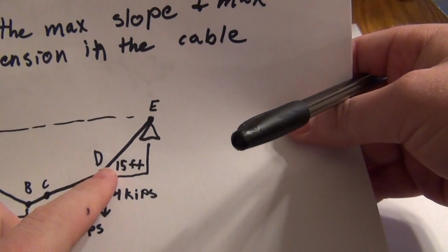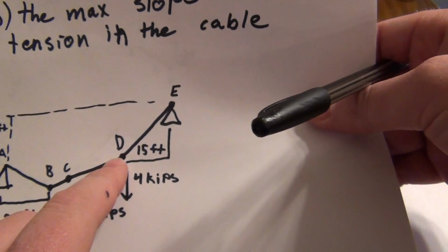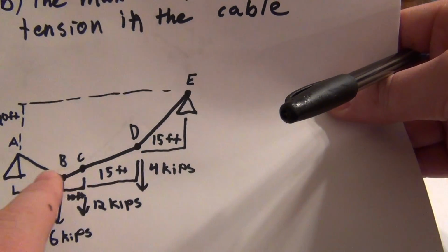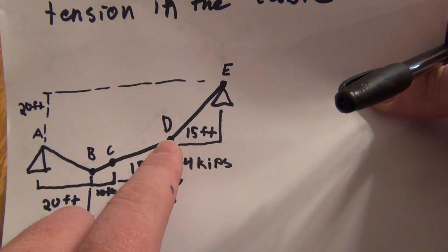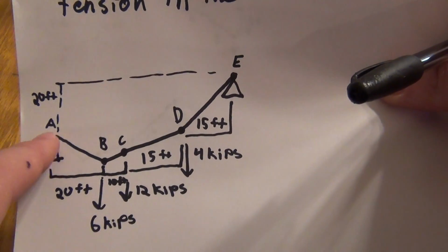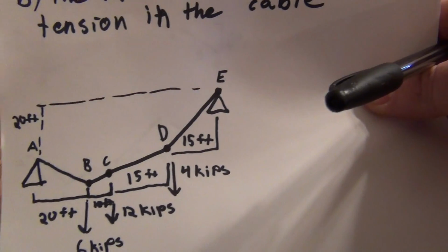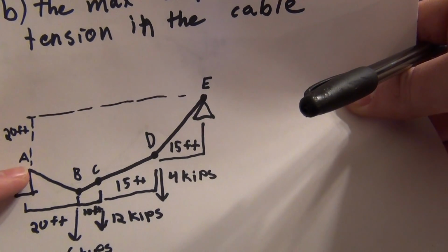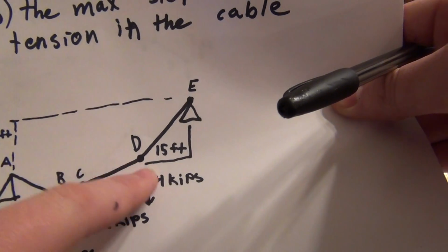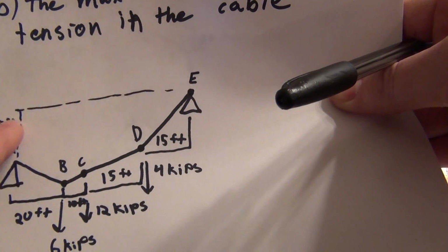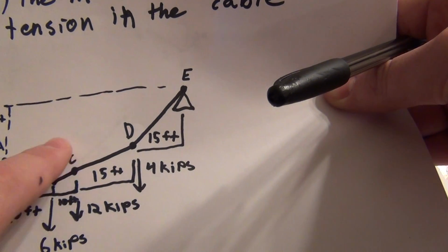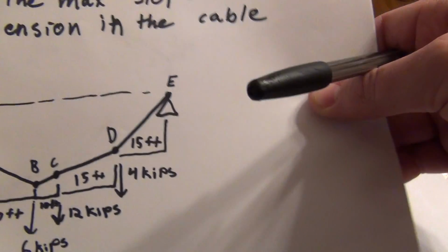So, looking at DE, now remember, D is not exactly shown well in this, but D is actually 5.83 feet above A. So that's going to be important, and that was our last answer, because we know that 20 feet is the difference between A and E. So the difference between D and E is 20 feet minus the difference between D and A.